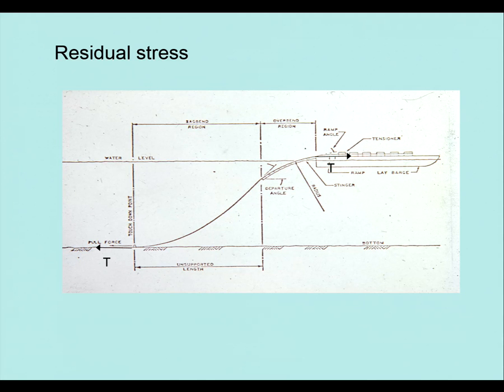You see that, you realise that, do you? If I've got the top of the pipe coming down like that, and I apply tension there, like in a J-lay, then that is the horizontal component of tension, and that comes round to there, and that's TH. That tension is not seen here. Only in shallow water does it apply.